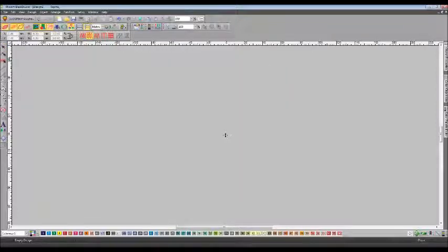Guides, the guides are accessible from the tool, the little ruler bar here. If you just click, it shows vertical and horizontal guides. They're great if you need to line up text. If you're hand digitizing lettering, you can use this to see where you want to cut off the letter or not. If you want to make sure the logo is straight, you can use these as guides if you've got a JPEG in here. But to get rid of them, you just left click and pull away and they disappear.